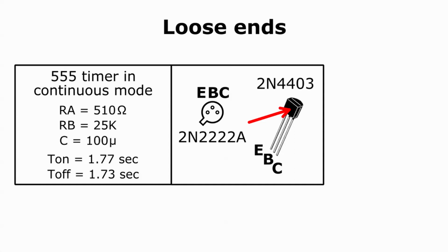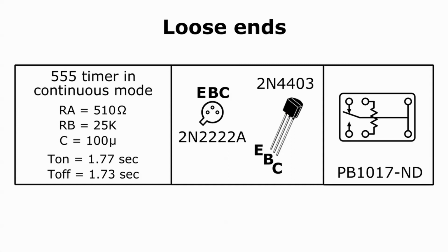This is the pinout given in the datasheet for the relay I used in the light flashing circuit. This is the top view. The coil has been drawn using the symbol for a resistor. The pinouts for relays are always shown with no current flowing through the coil, which is to say, in the unenergized state. We can therefore tell that the normally closed contact is the one at the upper left, and the normally open contact is the one at the lower left. There are two pins for the common contact, one on either side of the component, to make it easier to wire into a circuit. That's all for today.